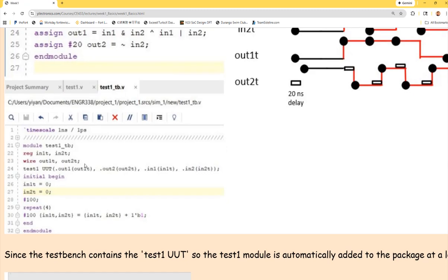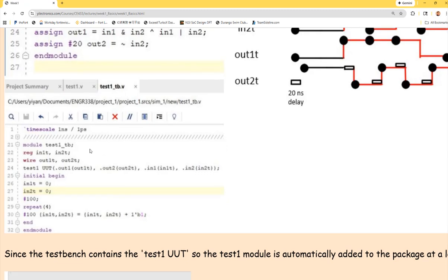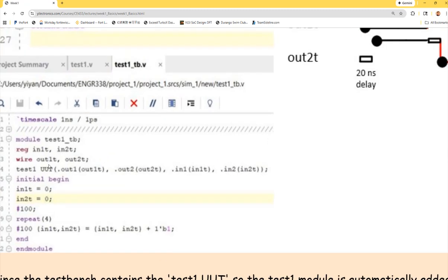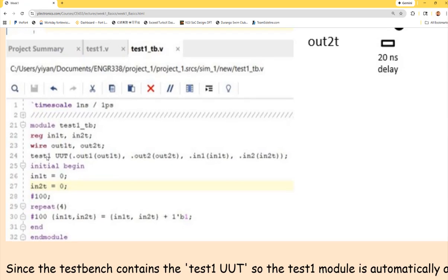And what is after that, if you are looking at the test bench over here? The test bench is nothing but bringing in the sub module of test 1, and you name it UUT. UUT is what? Unit under test. Because it's a test bench, it's just the unit under test. In the lab on Tuesday, the name we had for the sub module was DUT, the device under test. Doesn't matter. You'll see UUTs, DUTs, whatever. You can name it whatever you want. And this is essentially your sub module here, and your initial design assigns values for the test bench.